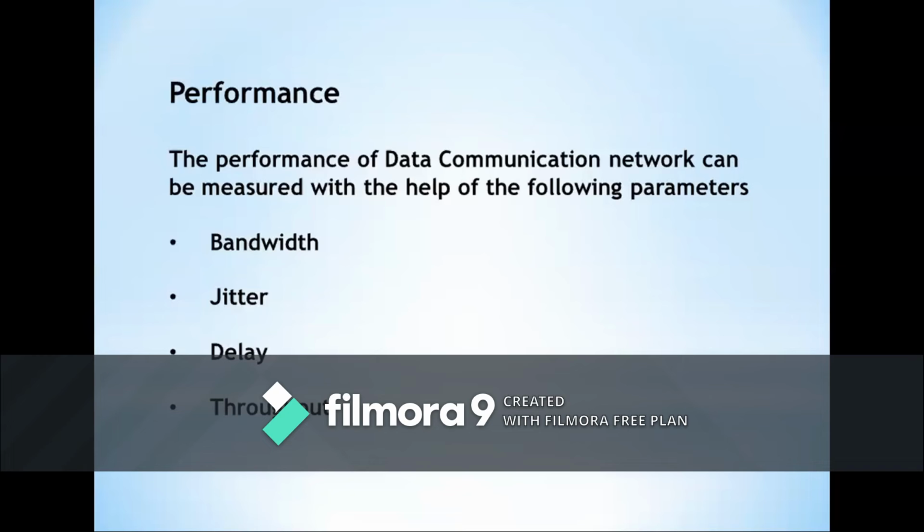Signal bandwidth is defined as the range of frequencies contained in the signal, whereas bandwidth of a channel is the range of frequencies that are passed by a channel. If the bandwidth of the input signal is larger than the channel bandwidth, the output of the channel will not contain all frequencies of the input signal. If the signaling rate of the input signal is increased, then the channel bandwidth has to be increased so as to pass the signal without any change in the shape of the signal.